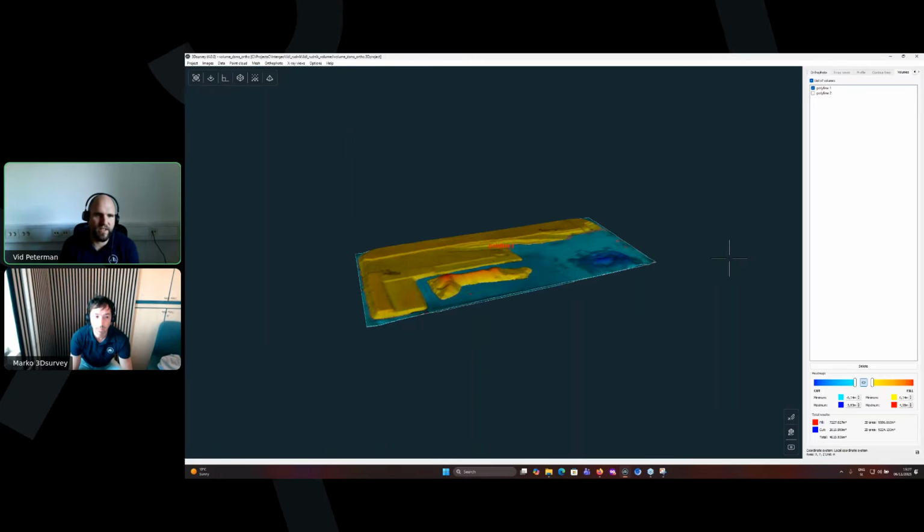So that part is always like that: the first step of processing for the LiDAR scanners, you always have to do in their software. But they always give you a free option of a software that will only do that conversion of the raw laser scanning point cloud into something like LAS or E57, something which is standardized and we can then use between different softwares.